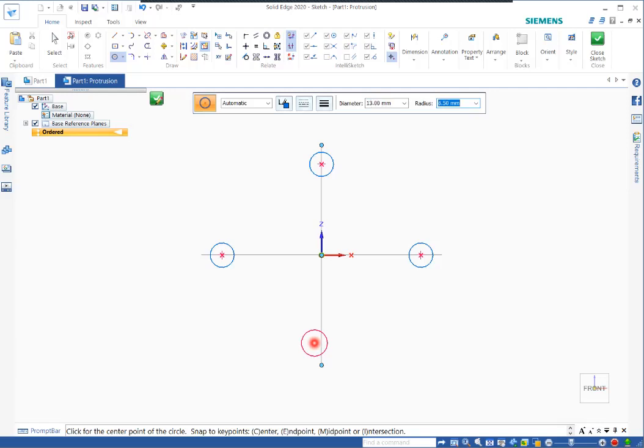Press enter. Okay, you have a slightly larger circle here. You do the same once the point on indicator appears, and click. When you draw the circle, not too close to the end, just leave some gaps here. Okay, click, and right click to cancel the whole command.